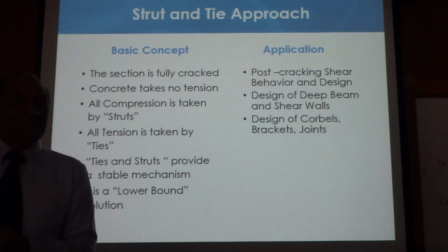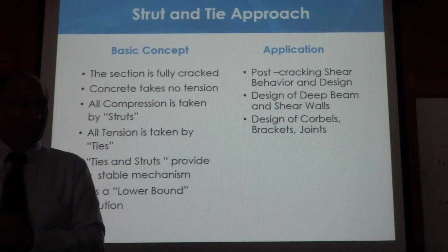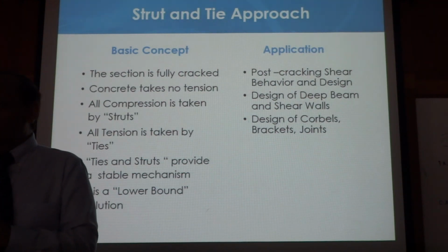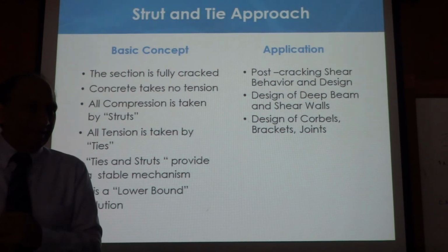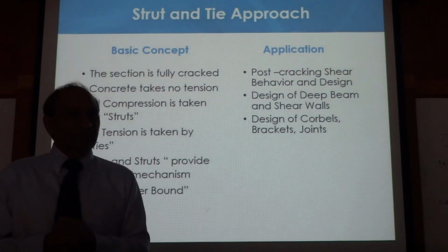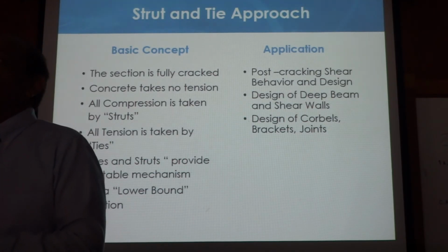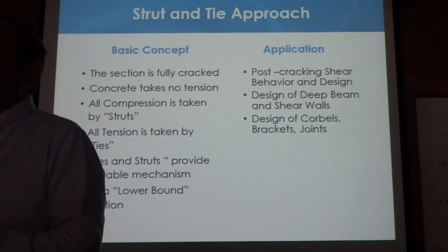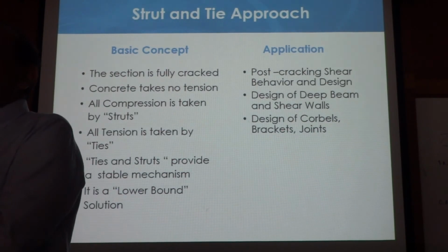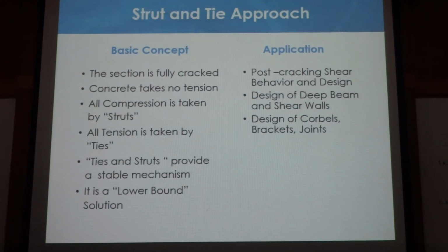You tell a client that has paid you a lot of money that your beam is going to be cracked, he will take the project away from you because he's not an engineer. They don't expect the structure to crack, but here you are assuming that the concrete is all cracked, right? So that means serviceability is not satisfied here in this approach, and we must do some other checks to make sure that the serviceability is satisfied.